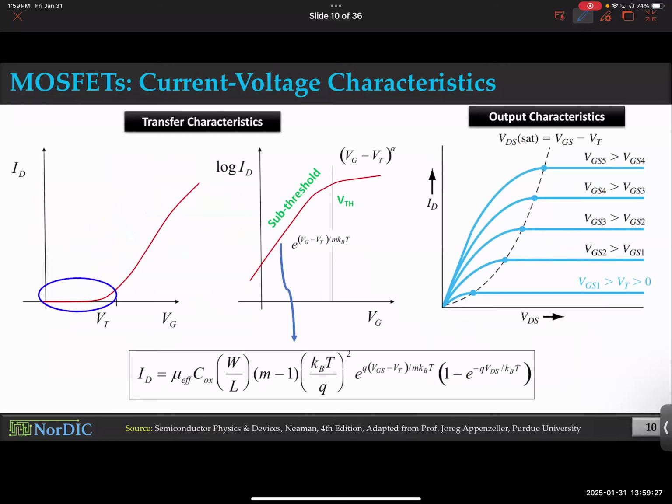So when people started realizing that, hey, something's wrong with our transistors, even when they're supposed to be off, they're leaking. So then they started looking at ID-VGS characteristics in a different way. So if I ask you, if I want to take a deeper look at this low current values, and I also want to see higher current value in the same graph, what is the best way to do so? The answer should be semi-log. When you plot something in logarithmic scale, the smaller numbers and bigger numbers, they both can appear in the same graph because there is a different scaling for both of them.